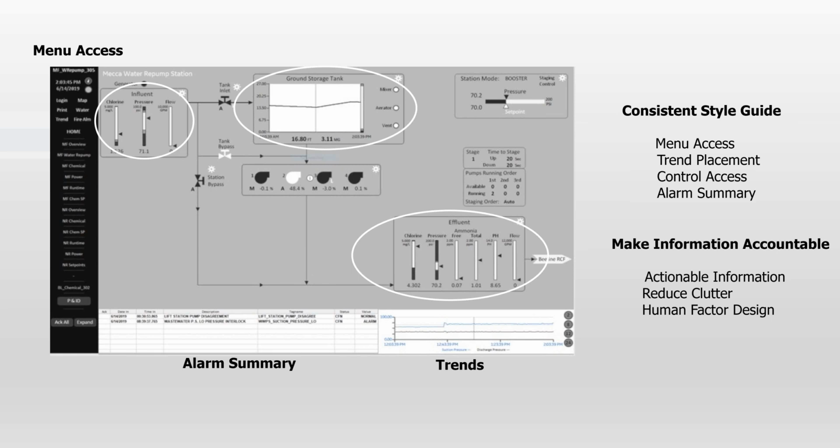Right up front and center is the process area that has a consistent look and feel of flow from left to right, top to bottom, and giving key indicators using the same style vertical bar graphs to indicate normal operation and alarming limits, tanks and other process levels shown as a graphical representation, and information grouped together to show a particular area of a functionality.